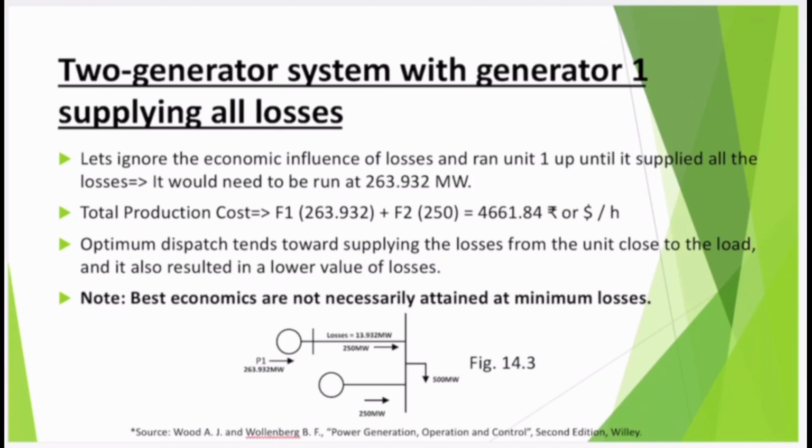So this is a wonderful example for all of you to understand that in case of economic dispatch without loss, we can easily solve the problem. But when you accommodate losses, then the sum of all the generators will be load plus the losses. Now, how to get my losses? The losses could be a numeric value, or it could be a function of my P1 or P2. When it is a function of P1 or P2, then using the previous equations, you can solve those equations and obtain P1 and P2 and its cost as well as the losses.